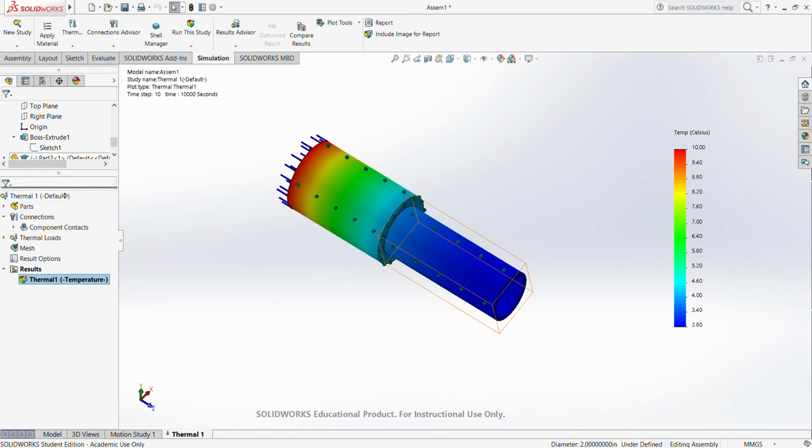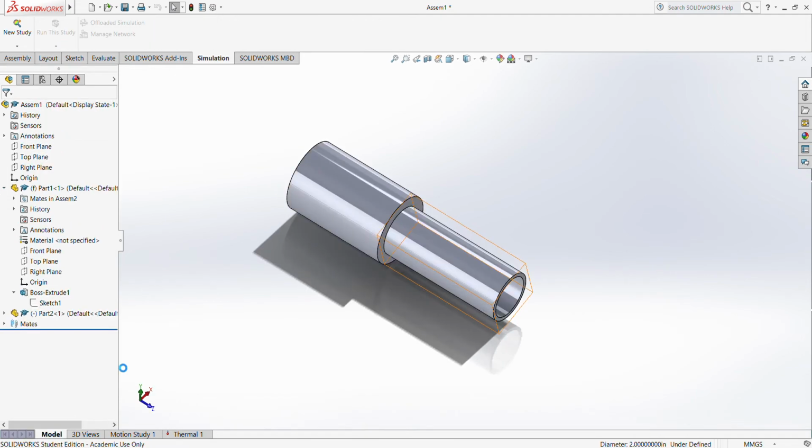For that we'll have to click model at the bottom, and we'll go to the Solidworks menu here. You go to tools, and you can say evaluate and mass properties. And now it's telling me that this is 370.92 grams. I'm not sure if that's enough. I don't remember how many grams the other one was.